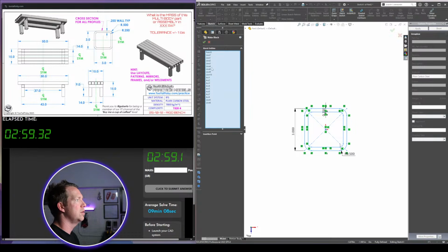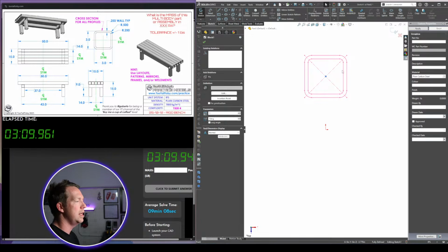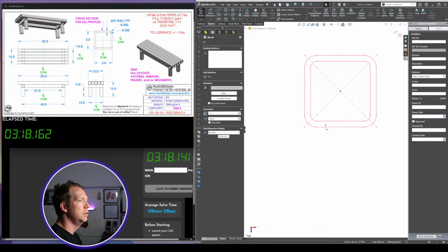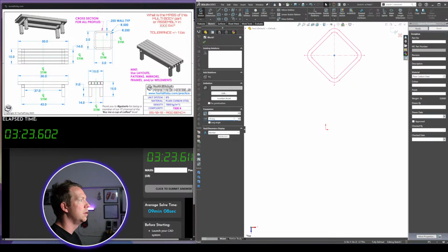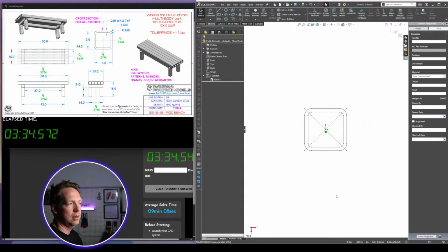Now although it doesn't say it, it also includes the dimensions that you have. Now once I press OK on the block, you can no longer see the dimensions. But the block is now a group of sketches that I can move around, and I can change the scale of the block. I can also change the angle. Alright, but where it's really useful is that I can make copies of it, so I can use that over and over. And I can still define to it, so I can grab that center point and drop it on the origin, and that's going to be basically fully defined. You can see it down here, fully defined.